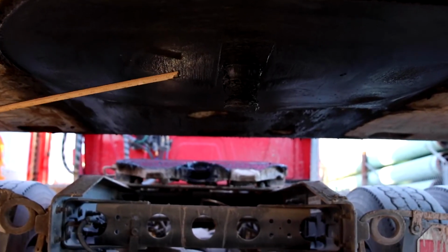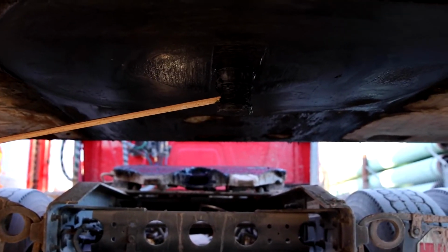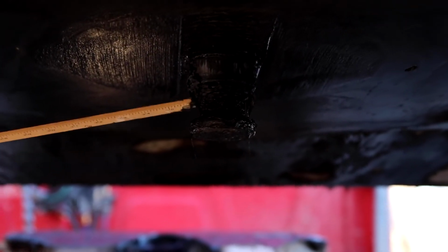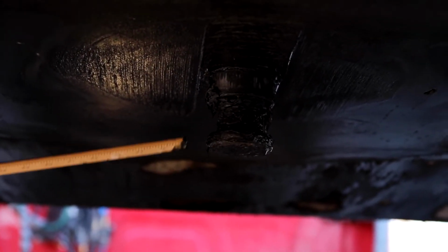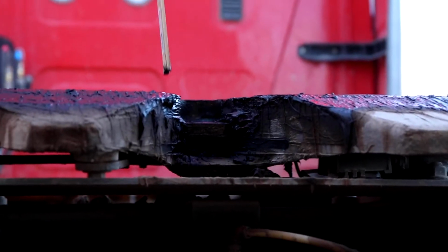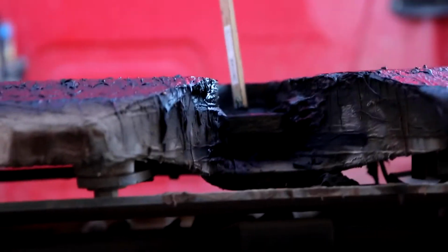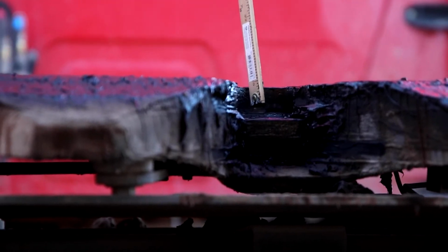Okay, this is your kingpin. This is the shaft, this is the shank, and this is the head of it. The shank, or the skinny part right here, is what the locking jaws of the fifth wheel will close around. Your locking jaws are right here. They will close around the shank of the kingpin. Locks the trailer into place with the truck.